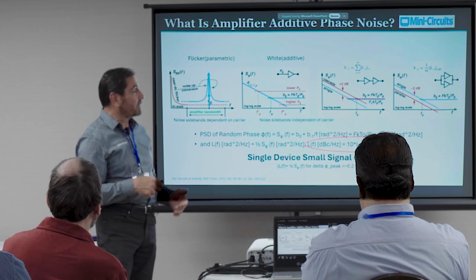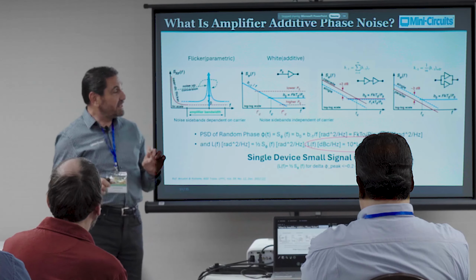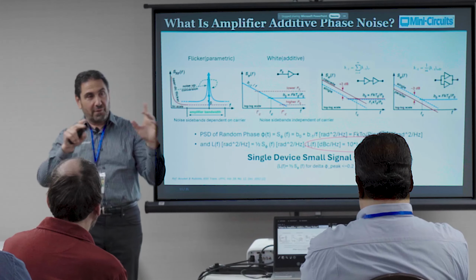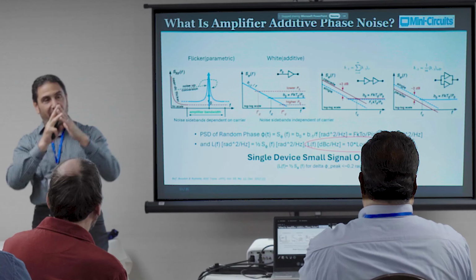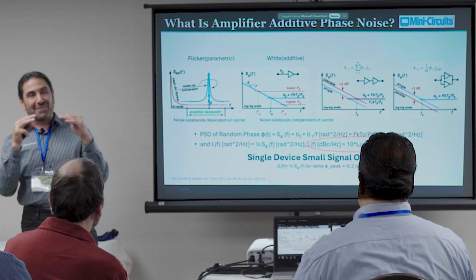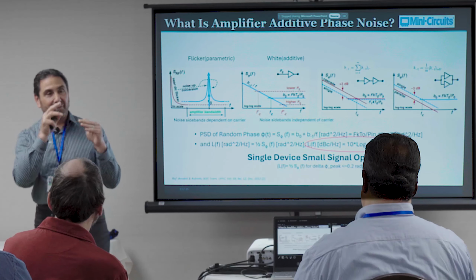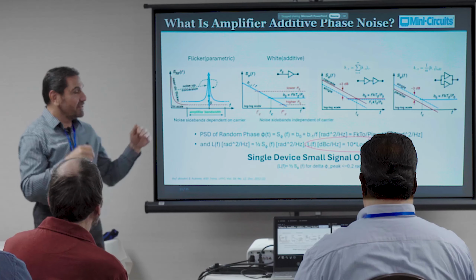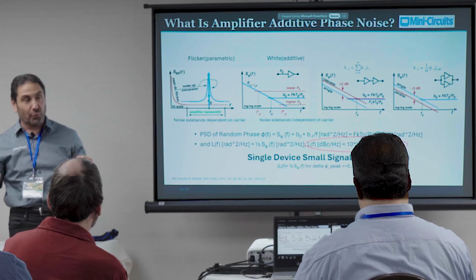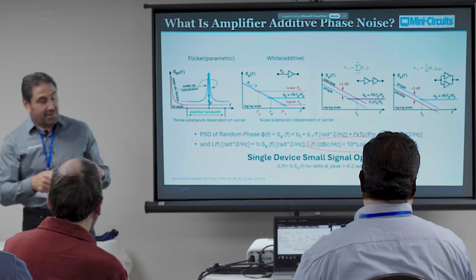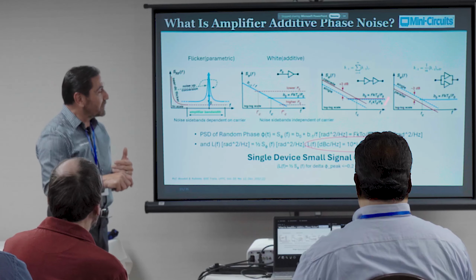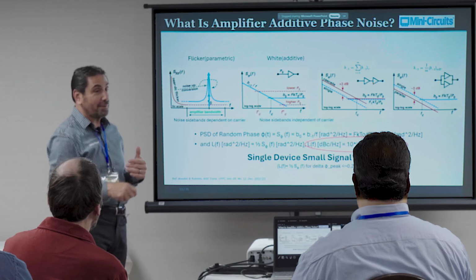It's power addition. If you go to the parallel case, it's a little bit different, right? The signal splits. You get two equal tones. They go through the amplifier. The 1/f noise for each amplifier gets parametrically upconverted to that carrier. But then they combine. How do they combine? The signals combine coherently, voltage addition: V1 RMS plus V2 RMS. The noise combines with power addition: the square root of V1 RMS squared plus V2 RMS squared. That gives you a 3 dB delta. So here you get a 3 dB log base 2 of m improvement in the 1/f noise when you put amplifiers in parallel, a degradation when you go in series.